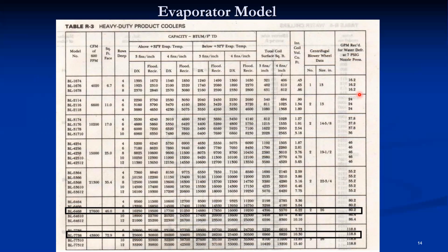It is also recommended here if chilled water is used. So based on that, for pre-cooling mainly, the recommended capacity is 4 fins per inch, because fast cooling is required. So the contact factor should be high, which means the bypass factor should be low. So for fast cooling generally